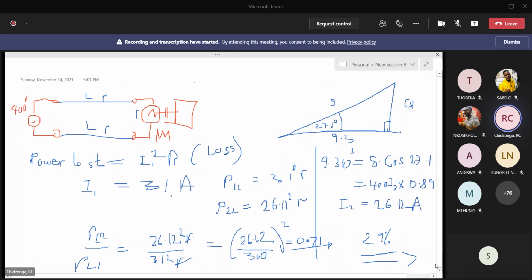On the other hand, if you had made the power factor even less, then you are going to see this picture. The scenario would be even 30% worse in terms of the consumption. So a reduction of current from 31 amps to just 26 amps corresponds to almost a 30% reduction in power loss.